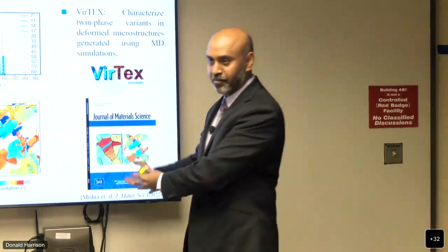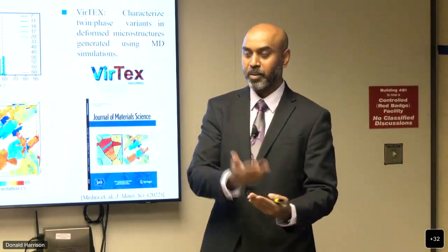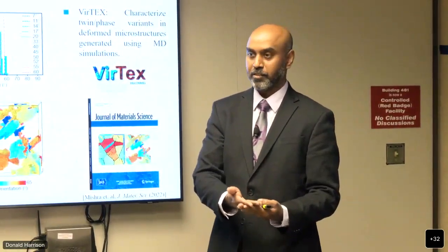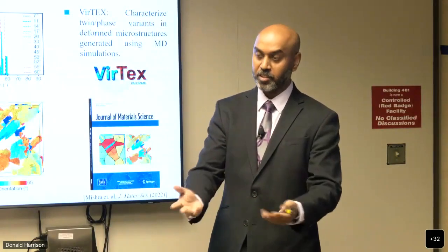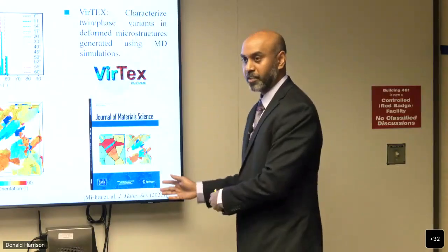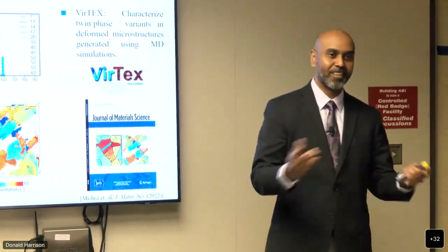But now that we have the capability, if there was an experiment where we're going to run that, you can characterize the microstructure well in advance. If you have a CT scan, we can import all of those orientations and build microstructures with the same orientations, shock the material, take diffraction patterns, and you run the experiment and look at the recovered microstructures, and we'll tell you what we think is a recovered microstructure as well. That is the big plan. Hope for us to recreate these experiments.